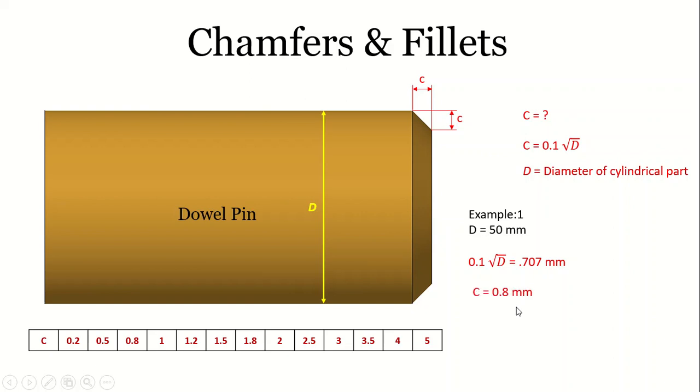So this is a very easy and good way to dimension a chamfer with a 45-degree angle, and this is what I use when I design any part where a chamfer is needed.